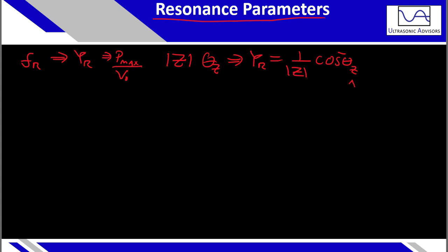And this again is going to have to be in radians. Just note very carefully that real admittance is not equal to 1 over the real impedance. That's due to complex number math, and that's not a process we'll go into in detail here, but just know these are not equal.